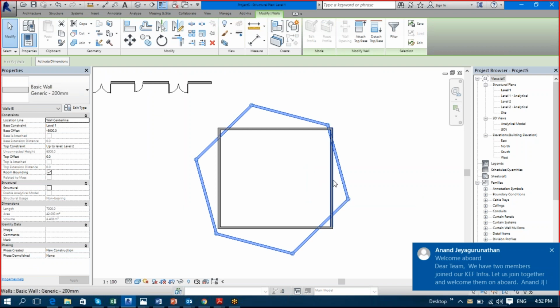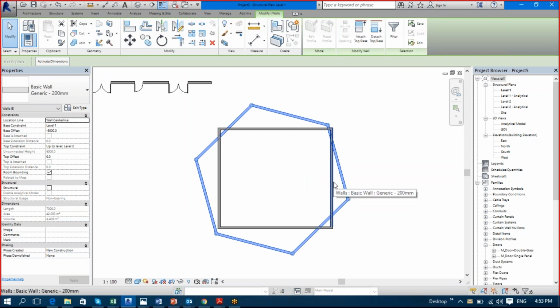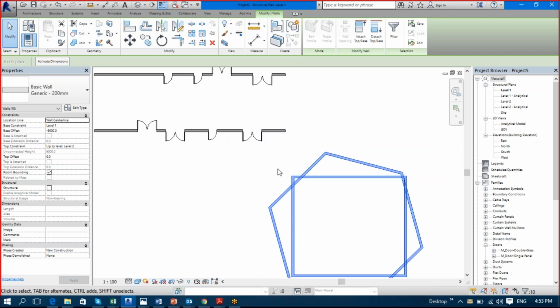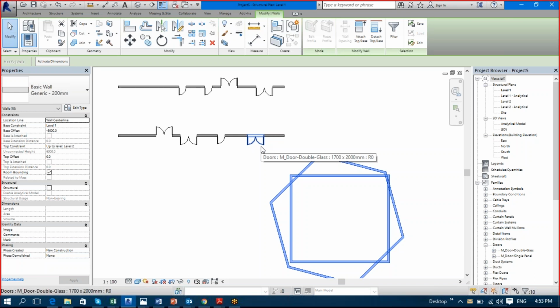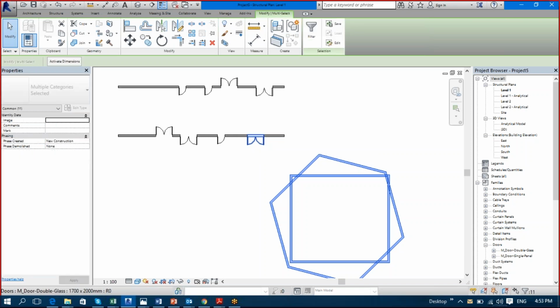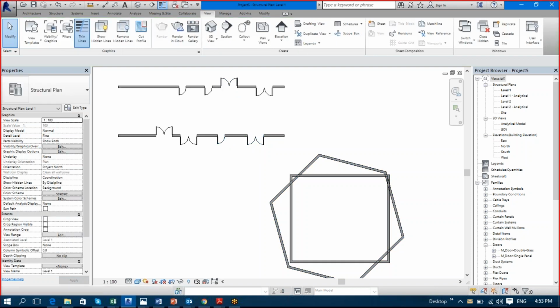And then again, I want this part also to be part of the selection group. I'll again press tab, and I'll press, what should I press? Then I click it. Now this becomes a part of it. If I want to add this thing into it, I'll press control. So control for addition and shift for subtraction is another way of doing things, and tab is a way of circulating inside it.